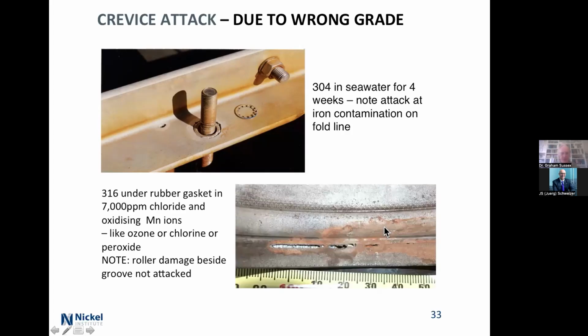This is plain rubbish. This is a piece of 316 pipe, Victaulic joint. So you basically cut the thing to length, roll a groove into the outside of it so that you're looking at the inside here. There's the roller where it was. And the seal is from the rubber gasket, which pushes onto the end of that and seals to the next one.